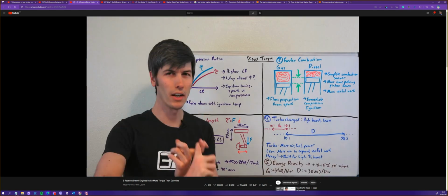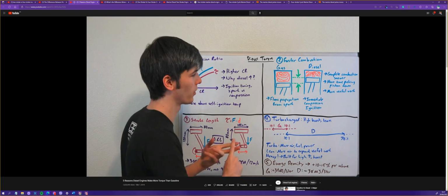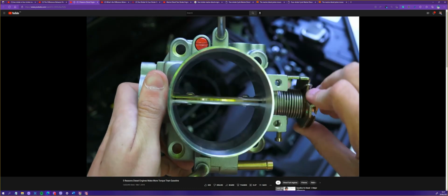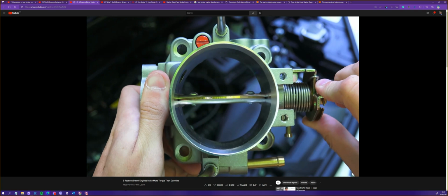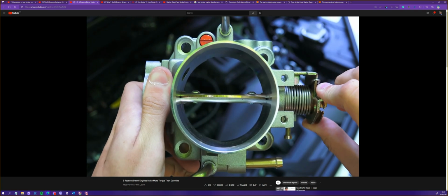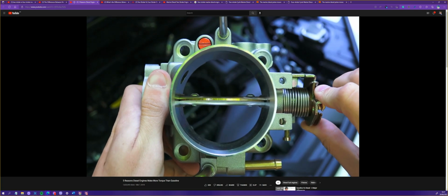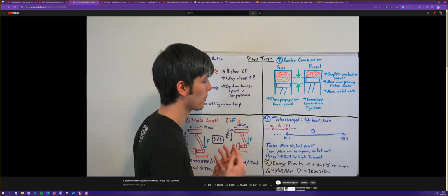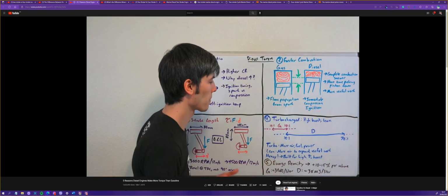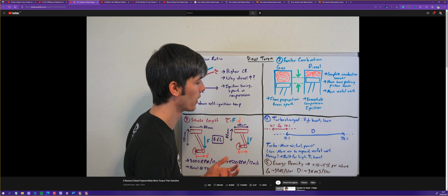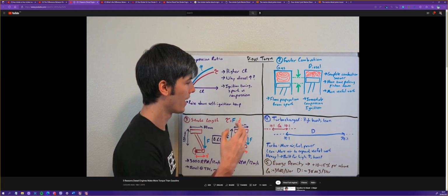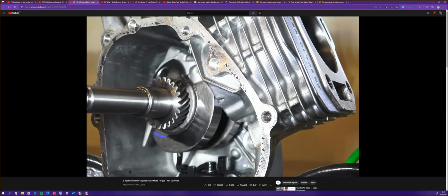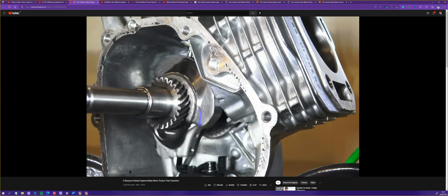They also don't have the pumping losses associated with gasoline engines, because they're throttleless, or typically have the throttle almost always wide open, versus gasoline engines which operate in a much narrower air-fuel ratio range. And overall you're not typically going to see as high boost levels, because gasoline engines aren't quite as built for those higher boost levels as diesel engines are from the factory. So again, more boost, more fuel equals more power and of course more torque.